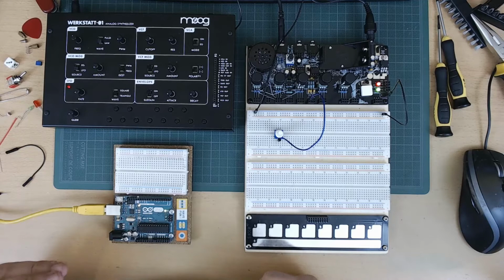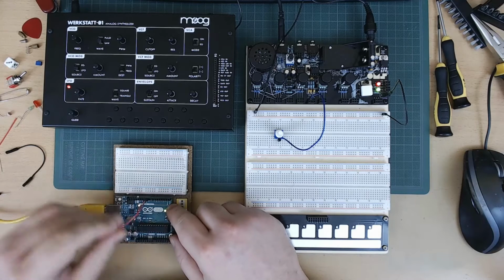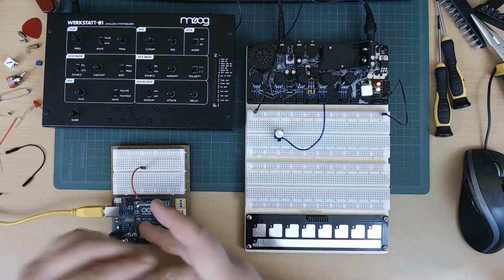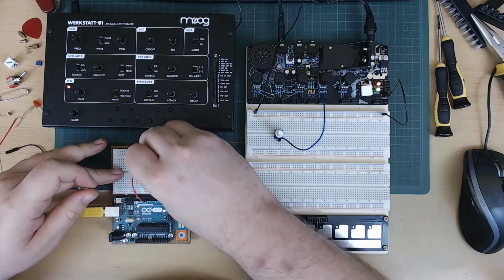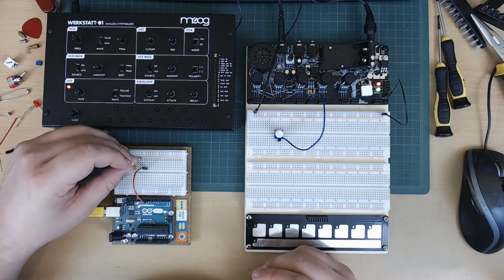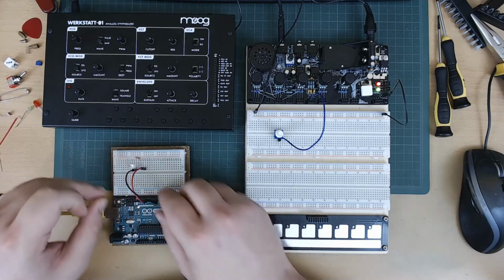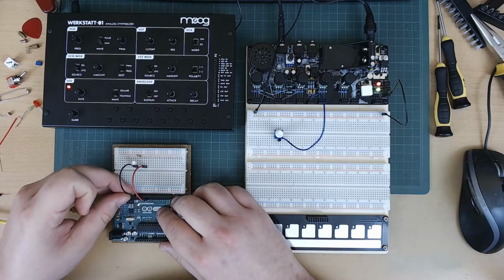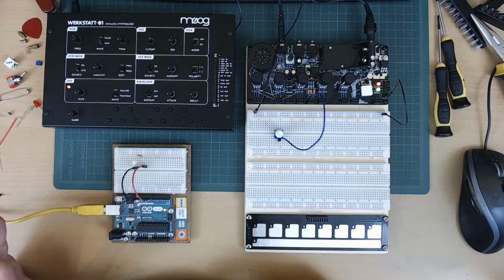Using that Arduino sketch, I can now use my pin 9 to power an LED, which is this one here. I'll put in a resistor to protect my LED, and connect the other side of the LED to ground. And as you can see, it now goes off and on, which is rather simple to do with digital pins.